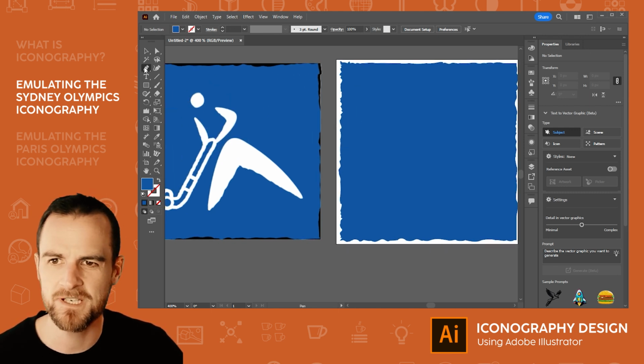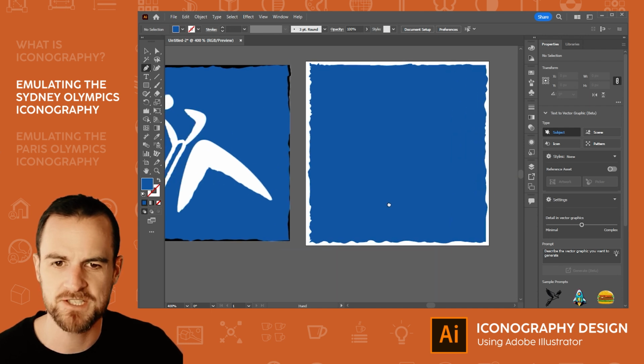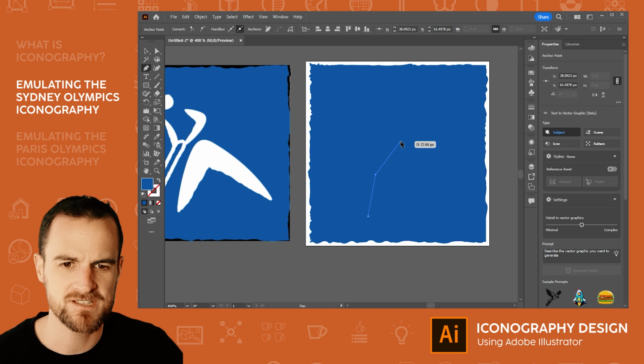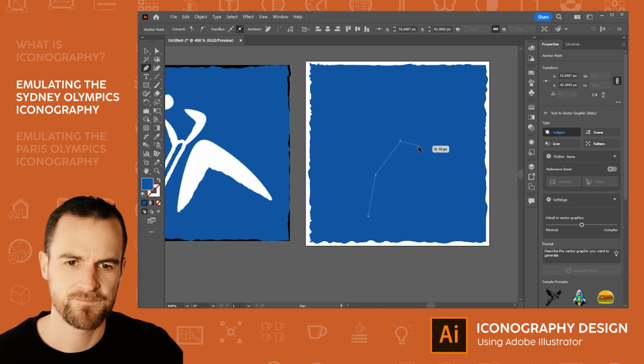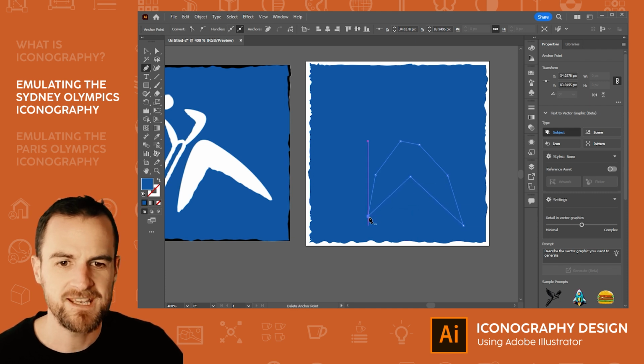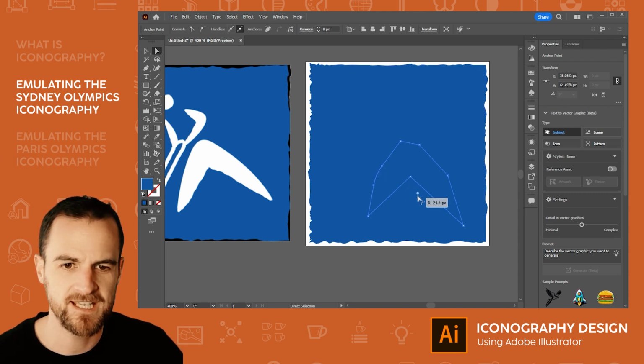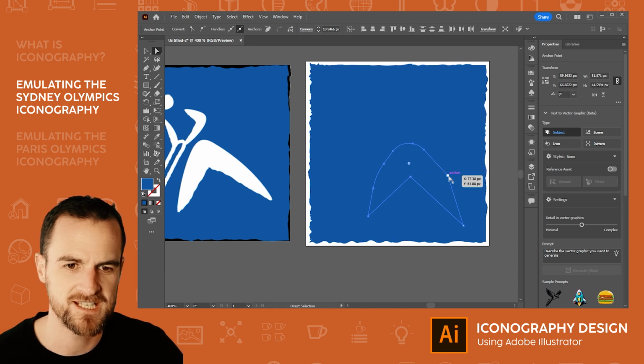All right, so now we're going to try to create this boomerang shape, and it's going to be effectively the same thing. So one thing that you can do, if you're not familiar with the Bezier tool, is actually just click like so, and just create a square of what you're trying to produce. And then you can click on your little white select tool here and just click on each node and round them off individually. So I just held the shift to connect both then. So that just gives you a lot more control.